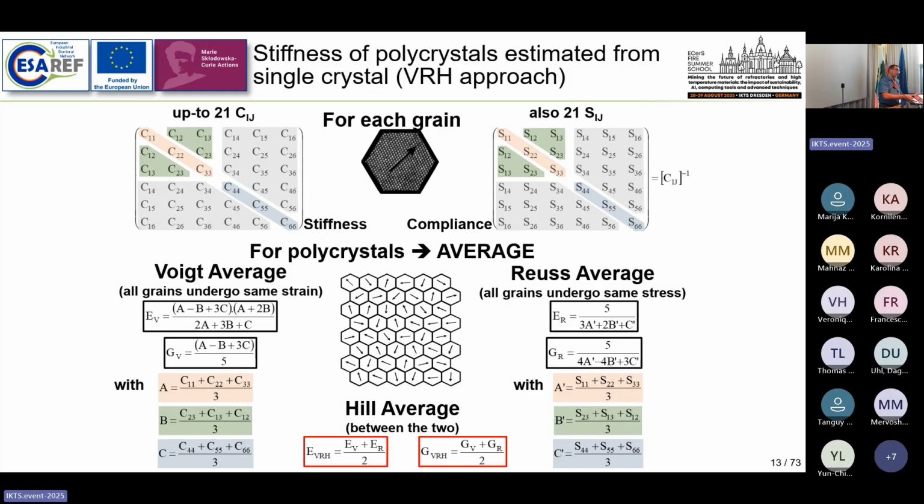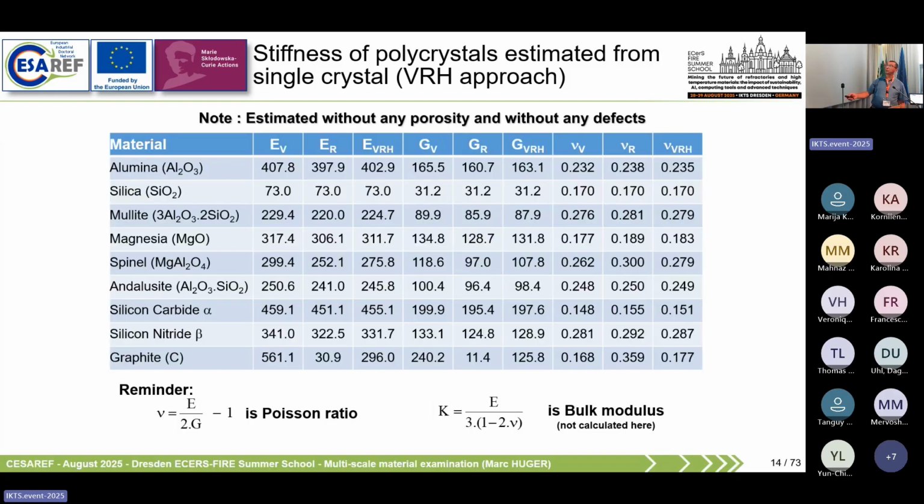In that case, if you look at the grains of alumina, which become isotropic due to the random orientation of each crystallite, then you can consider that this is an isotropic material, even if at the crystal scale this is a non-isotropic material. So it could help you to move to the intrinsic property of each crystal you consider, each polycrystal that you consider as a pure system without any porosity.